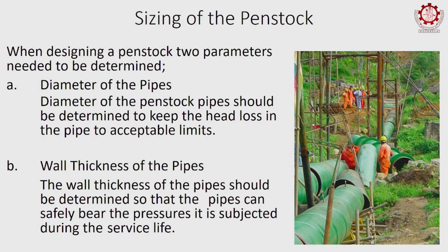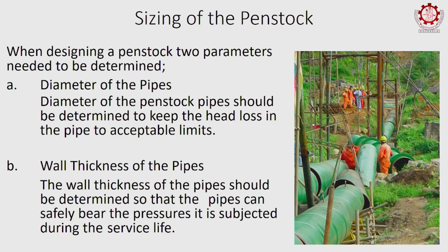So, you can see each piece; you can't handle two heavy pieces. So, we limited each piece weight to about 2.5 tons maximum, so that the people can handle them with manual means, because you have to align them perfectly before welding, right.